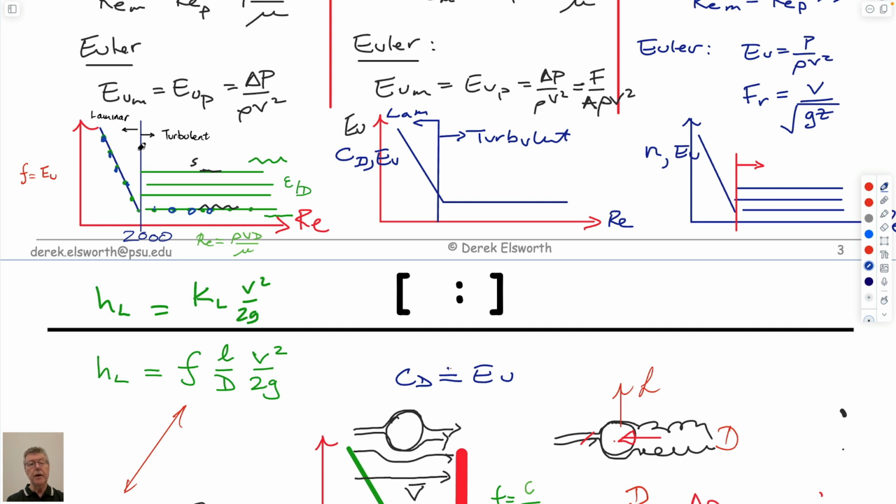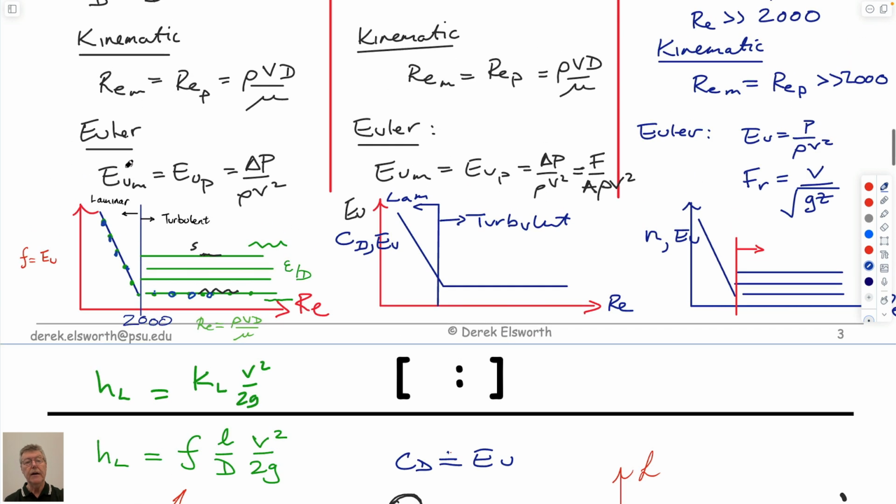And so by doing the experiment in the right Reynolds number regime, laminar or turbulent, you have kinematic similitude, so you're exactly the right Reynolds number, and you're measuring the right force in your structure. And so we can construct these figures, and we'll use them.